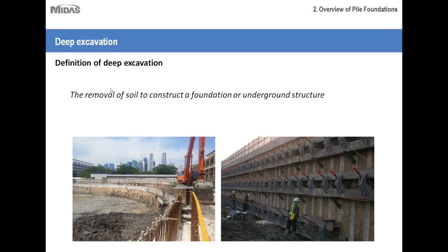A deep excavation involves the removal of soil to construct a foundation or underground structure. As geotechnical engineers, I'm sure you're all very familiar with this process. Whenever you want to construct a foundation, you'll have to dig out the earth first. Then, when you do that excavation, you'll have to support the soil wall surrounding it so that you can allow workers to work in safe conditions. And usually, the deeper your excavation becomes, the more rigid, or the larger in scale, these support structures need to be.